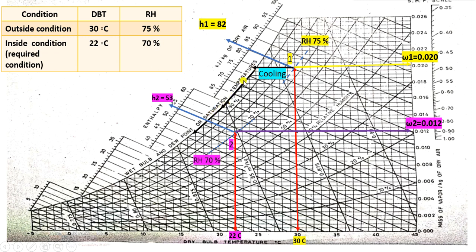Here they have mentioned saturation temperature. This is the saturation line. When this cooling line touches the saturation line, then from there the dehumidification starts. It will take up to here. Now you can ask the question, why do you have to stop here only, why can you not extend? Because point number 2 is here only. This is the dehumidification process up to here. Now I will start heating, so from this point to point number 2, it is the heating process.